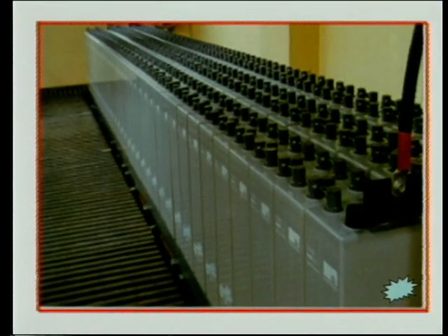Suppose any fault occurs in the power station, then the total system collapses. At that time, I want to know which breaker is in the on position, which isolator is in the off position. But then there is no power, there are no indications. At that time, I can take the supply from the charger, that is the batteries. It must be kept in a separate room and maintained every day. Here is an example, you can see how the batteries are in stations. They are continuously charging, and we can take the supply whenever we require.